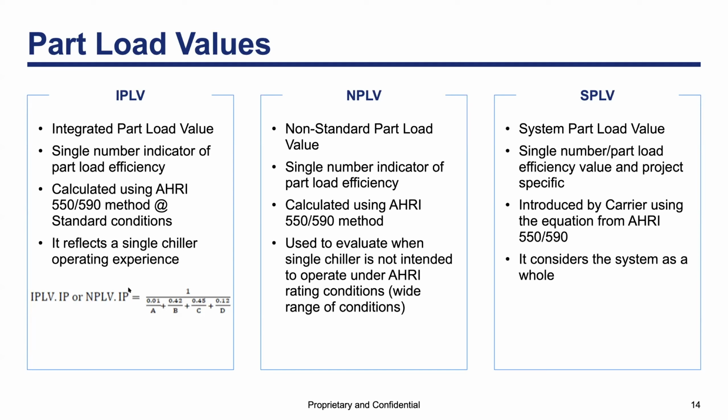Keep in mind, once again, IPLV and NPLV are metrics for a single chiller. If we take into consideration that energy consumption is a function of building type, load profile, weather conditions, type of chillers, whether constant speed or variable speed, chilled water pumps, and condenser water pumps, we can conclude that neither IPLV nor NPLV is good enough to define a comprehensive energy analysis of the system.